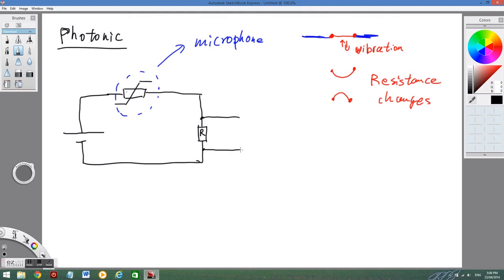say if I connect something, we can basically convert the sound into a signal like this. Okay? You see those electrical sound signals like that, because when I'm talking, the thing in the microphone moves backward and forward, thus the resistance of the microphone increases or decreases, and if I record the voltage across here, I record a signal like this.